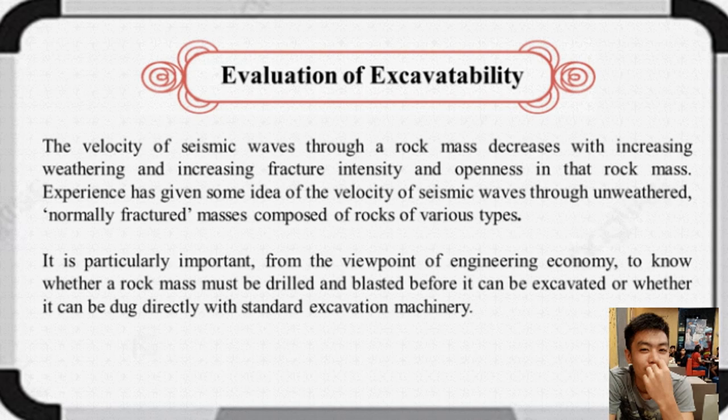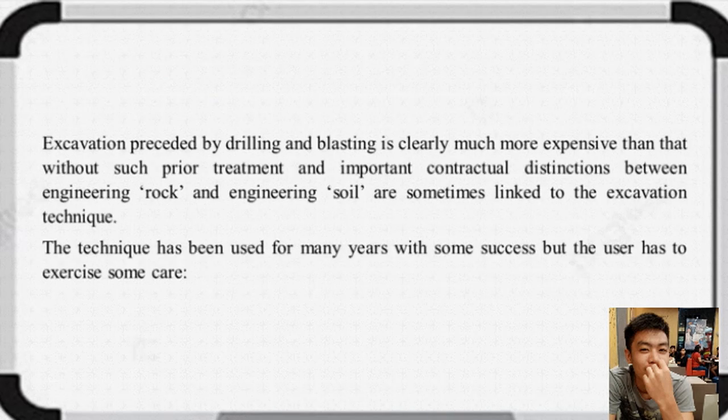So it is important to balance in engineering economy whether the rock mass will be drilled and blasted before being excavated or dug directly with standard excavation machinery. Excavation preceded with drilling and blasting is clearly much more expensive than that without such prior treatment, and important contractual distinctions between engineering rock and engineering soil are sometimes linked to the excavation technique.